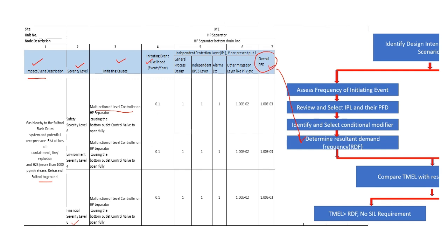Because HAZOP is mainly the process of hazard identification. So it will identify the hazard, and LOPA is basically a technique of hazard reduction. So it is more focused towards reducing the hazard. So we do HAZOP for identifying the hazard and do LOPA to reduce the risk.